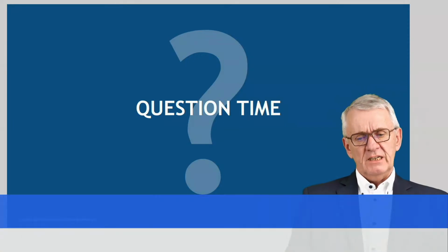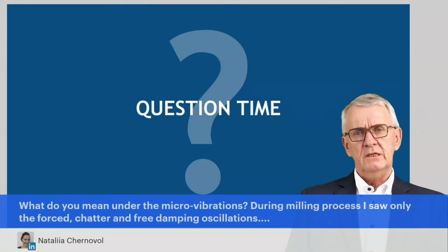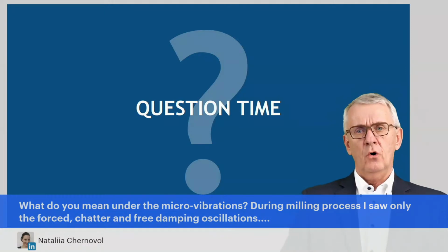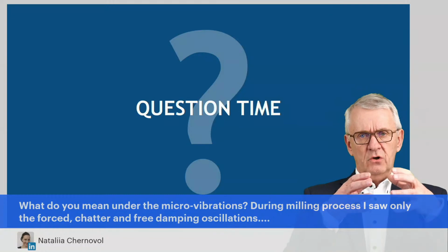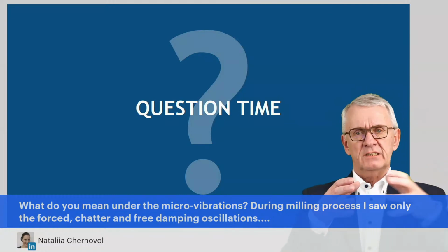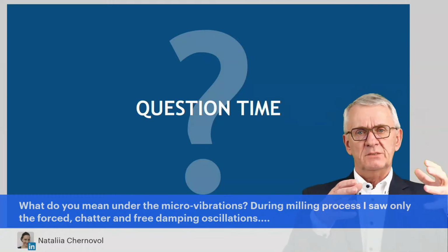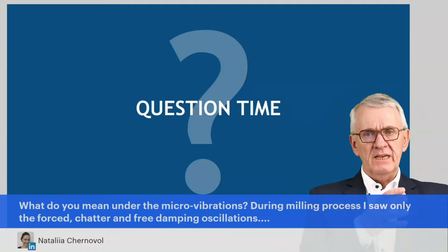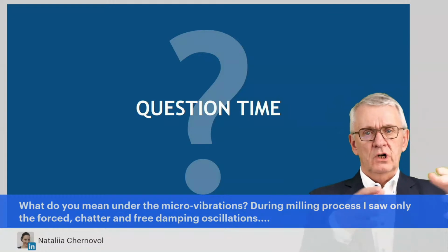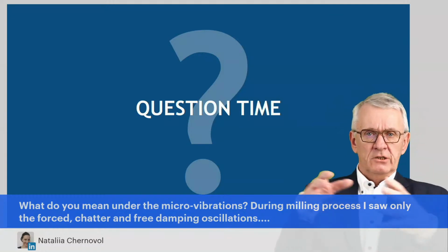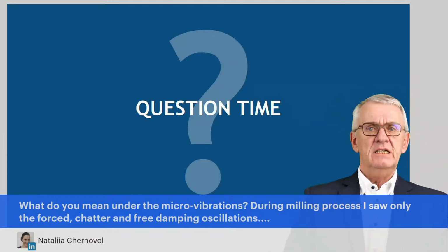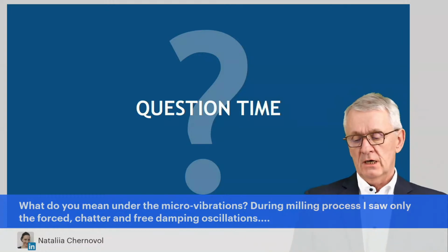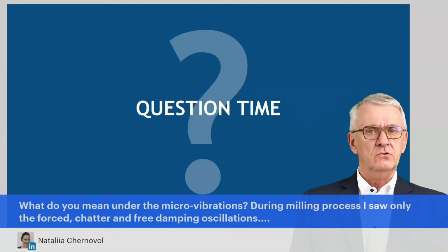The traditional vibrations you refer to, that could lead to chatter and so on, are vibrations due to the whole milling cutter, compared to the workpiece, bending, and due to the bending it starts to swing, kind of. That can lead to a macro vibration, as it is referred to. In the end, it could lead to chatter.